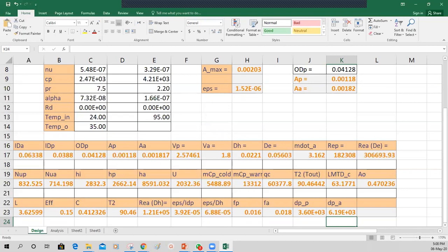Okay. So what is the constraint for the pressure drop? How much pressure can you bear for the heat exchanger? The constraint given in your book is 70 kilopascal for the pressure drop. The actual constraint comes from the industry, depending upon what pumps are available in the market and their cost. As you go for higher pressure developing pumps, their cost increases exponentially.